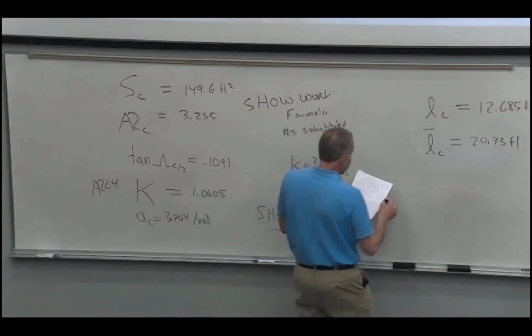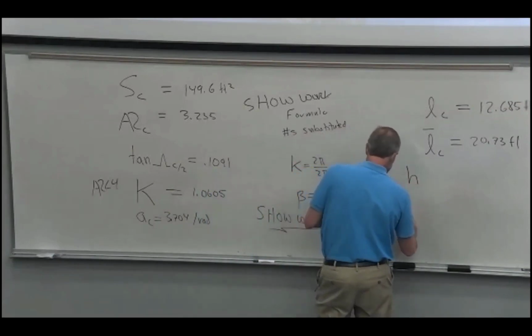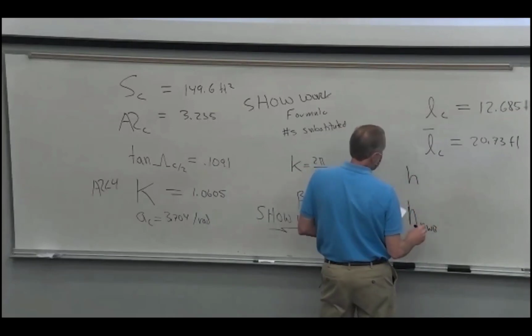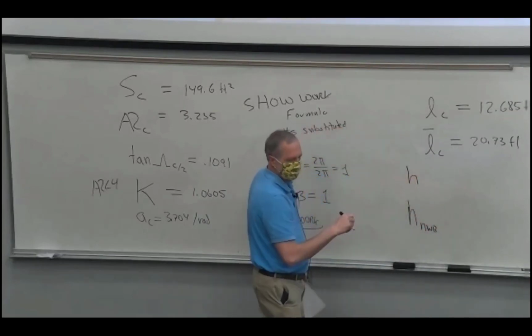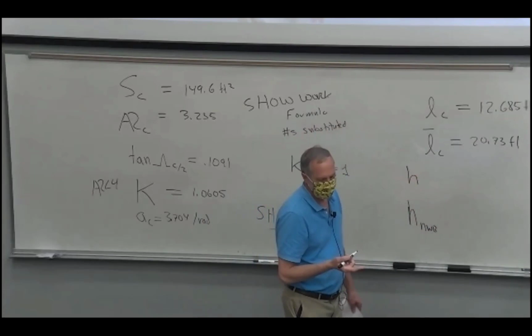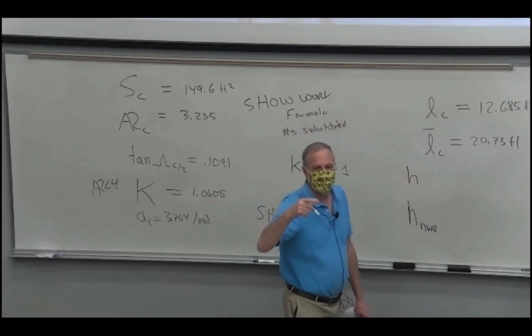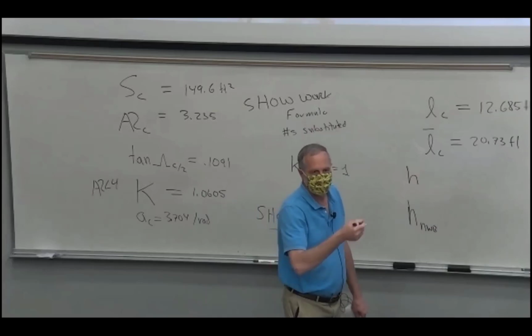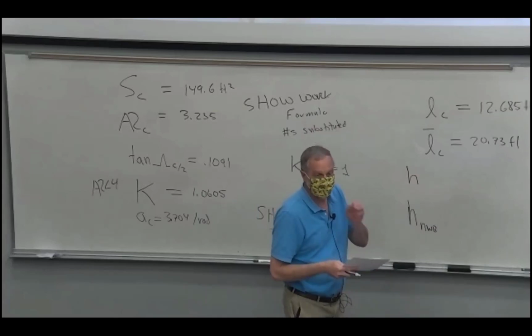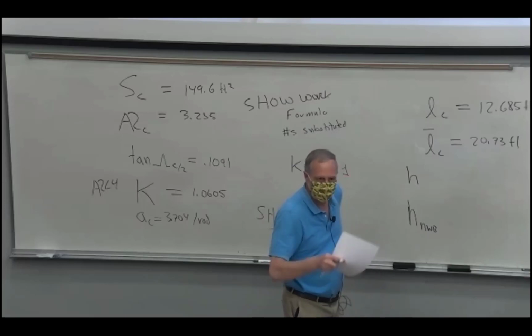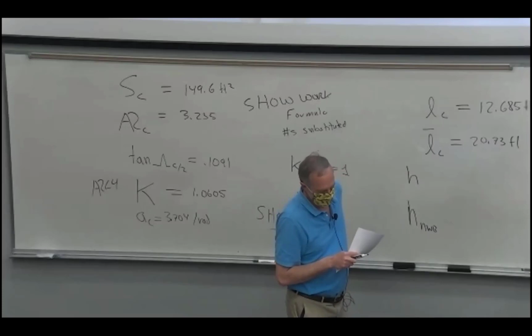And then it asks you to calculate H and HN wing body. And you're given X, the distance to the CG, is 2.75 on the figure. It's forward, so it's negative. And that's said in the homework. We define that as negative forward, based on the way we've defined H before. It's always positive aft of the CG.